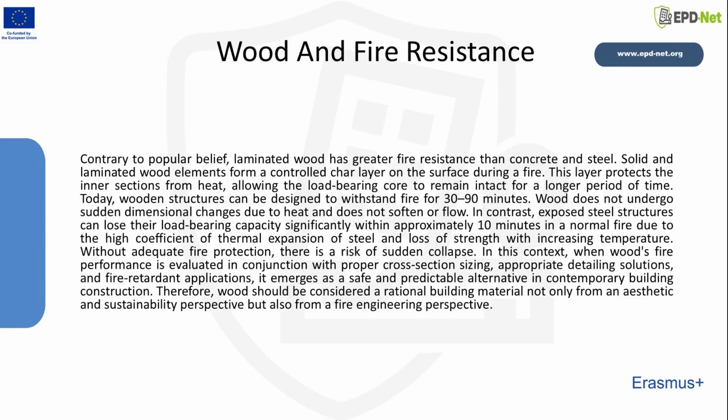Contrary to common assumptions, laminated wood can show strong fire resistance when properly designed. Solid and laminated timber elements form a control char layer on the surface during fire. This layer protects the inner sections from heat and slows down the burning process. As a result, the load-bearing core can remain intact for a longer period of time. Today, wooden structures can be designed to withstand fire for 30 to 90 minutes, depending on design requirements, element size, detailing, and fire protection strategies.